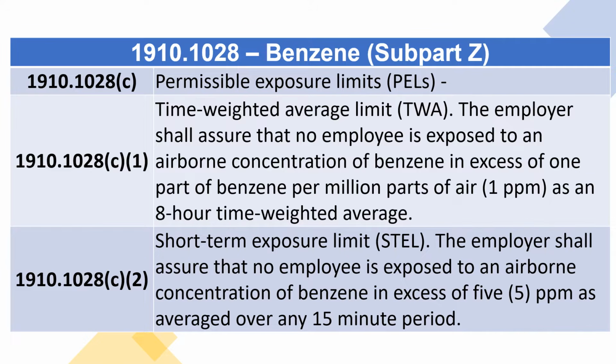1910.1028 C2. Short-term exposure limit, STEL. The employer shall assure that no employee is exposed to an airborne concentration of benzene in excess of 5 ppm as averaged over any 15-minute period.